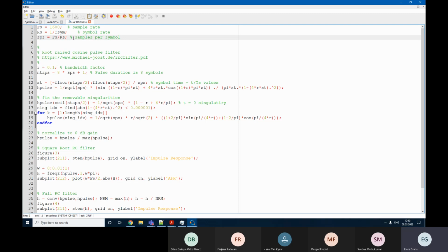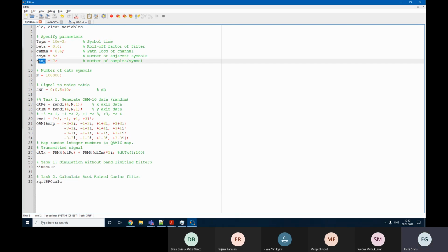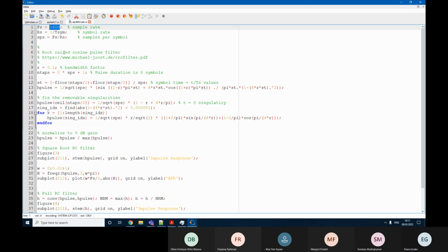The sample rate is going to be n SMP times greater than symbol rate. So that would be n SMP divided by t symbol. Accordingly, if we divide these two values, then all that is left is NSMP here, yes, and automatically we achieve what we want. Next step, we need to specify bandwidth factor.